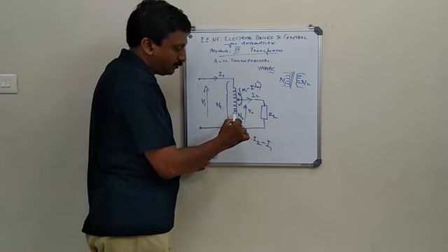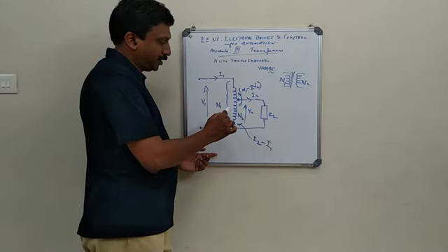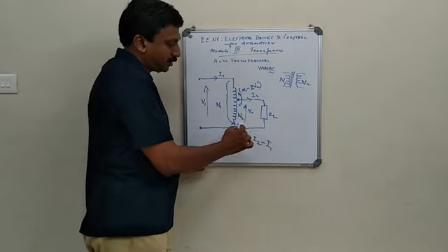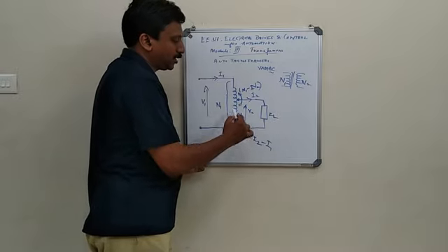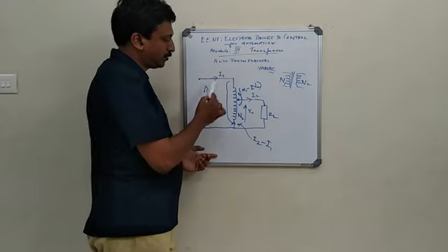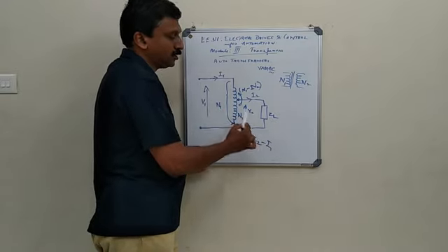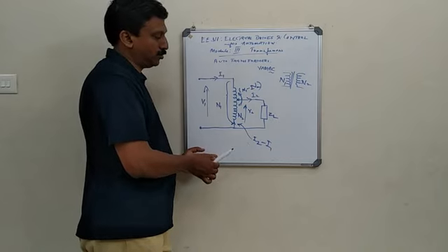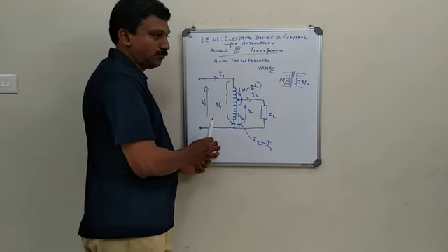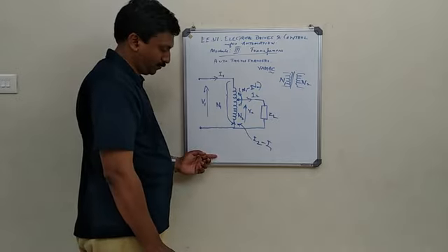So conductively and inductively, there is a transfer of power, and this power is actually given to the load. So from the supply, these two means of power transfer are there in the autotransformer. This is how your autotransformer works.